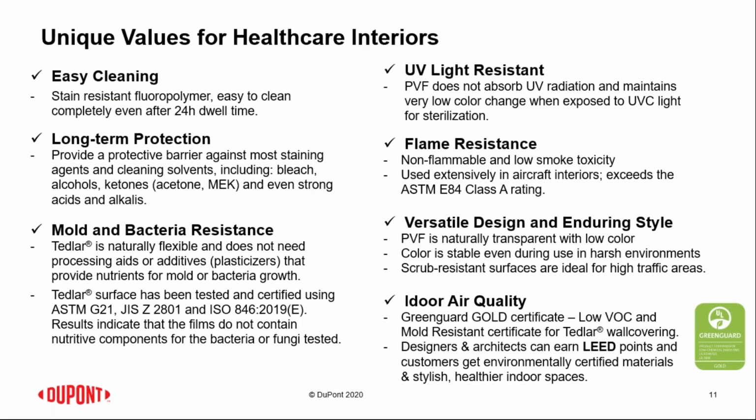So, the value of Tedlar in healthcare interiors. First and foremost is easy cleaning. The fluoropolymer is stain resistant. Staining agents tend to stay on the surface. And even if that staining agent is left on the surface for 24 hours or longer, it's easy to remove it without leaving any stain or ghosting behind. The Tedlar is easy to clean and disinfect because it's resistant to a very wide variety of cleaning agents and disinfectants, including bleach, alcohol, ketones, even strong acids and bases.